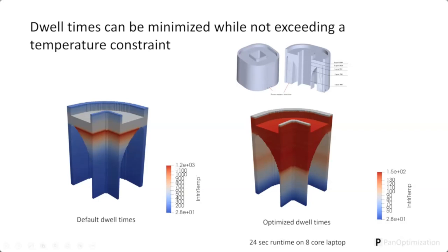Now this was like 1200 degrees. I said I don't want to go over 150, and it's brought this entire region of the part into a uniform 150 degree interlayer temperature. And these things again run very quickly. So this is just a 24-second runtime on my laptop.